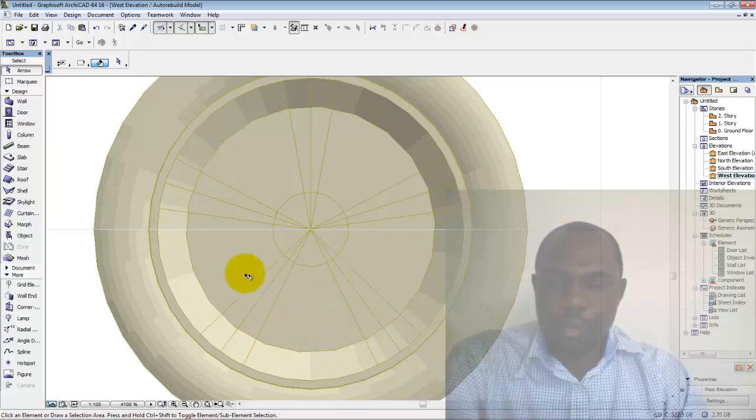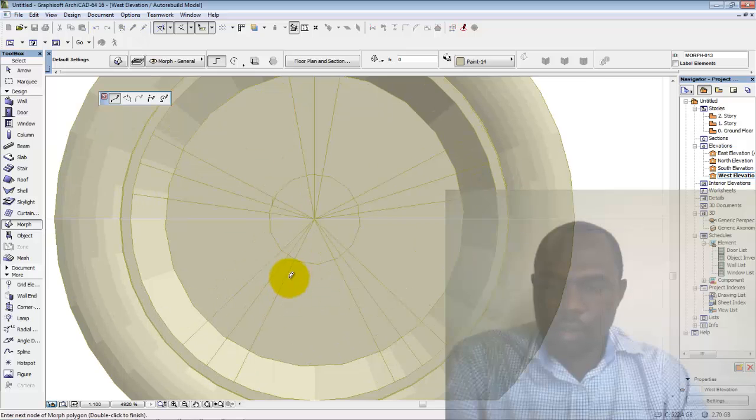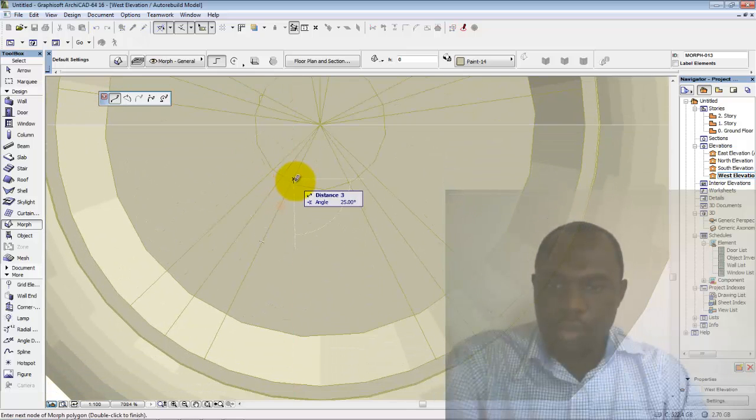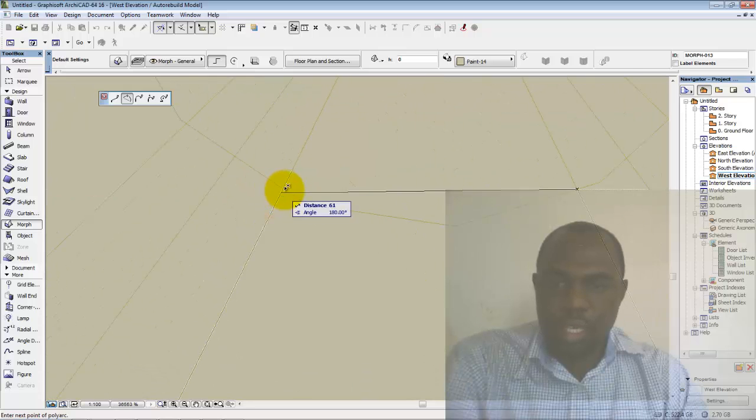within this area. So we'll move on to draw the shape. So we just click here. First click was not exactly on this intersection, so we move on to make sure we're going to get it at this intersection. Select the arc by 3 points, draw the radius, we go back to this straight line, draw this one, go back to the arc by 3 points, then make sure we select this point so that we get things right.